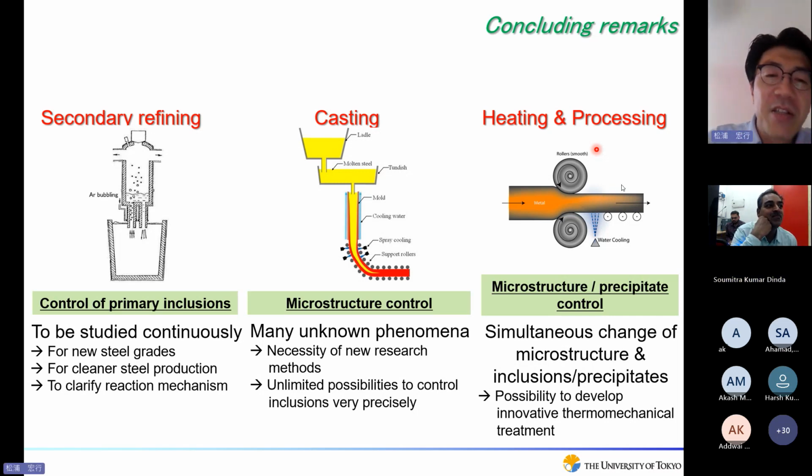No, I think it depends on the steel products you want to produce. In the electroslag remelting process, as you know, the molten steel travels within the molten slag. During that process, some existing inclusions already in the starting materials can be absorbed by the molten slag.